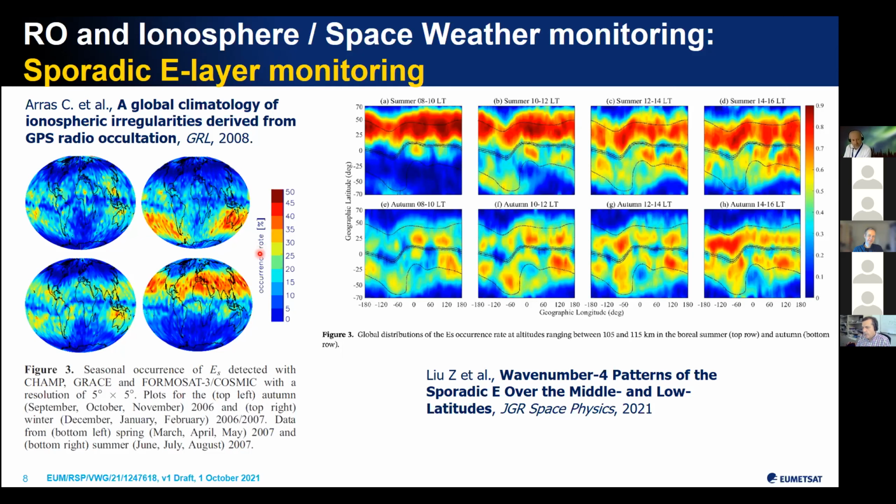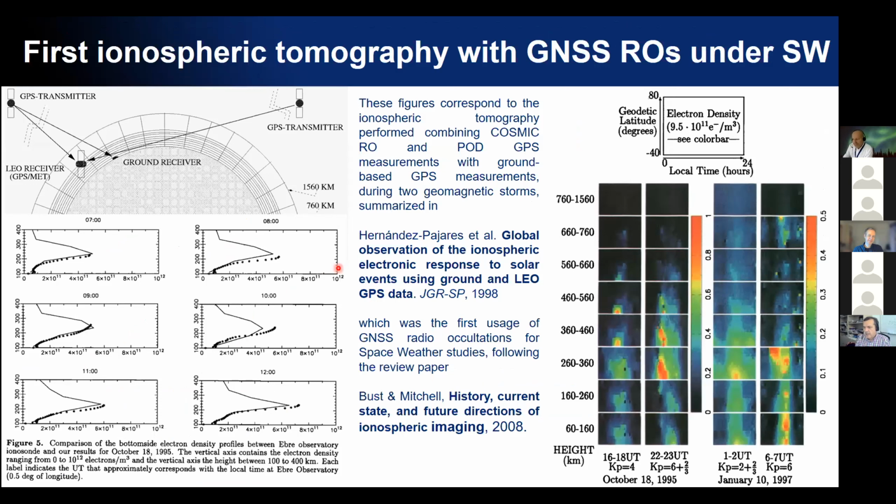Okay, in the next slide, we have an example about data simulation that we mentioned at the beginning. We can combine radio occultation data beyond the assumptions of the Abel inversion or the improved Abel inversion with, for instance, ground data, because both have complementary properties, which makes global tomography much more feasible.